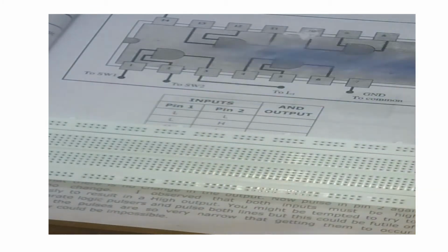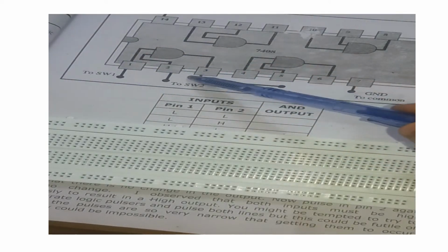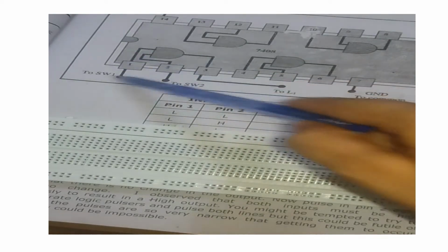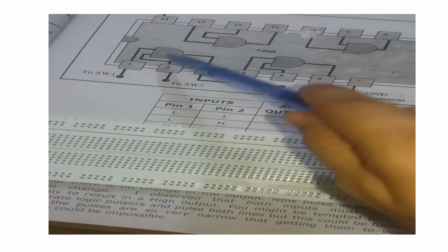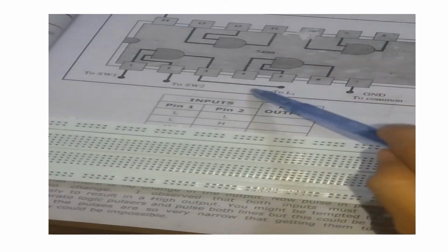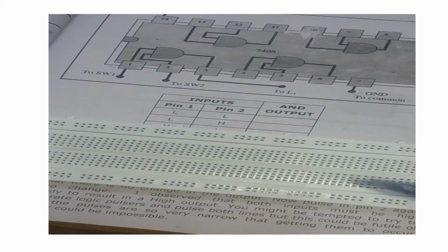The 4 AND gates can also be used in designing other gates, but to verify the AND gate we draw, design and verify the truth table for only one gate. If you want to check whether all the AND gates in the IC are working, you can check them one by one.